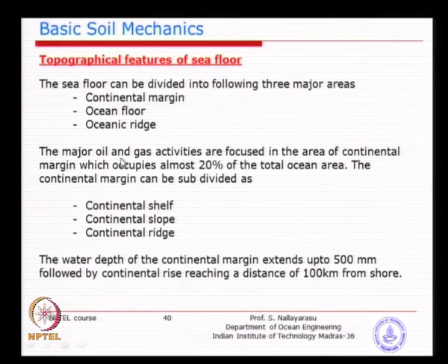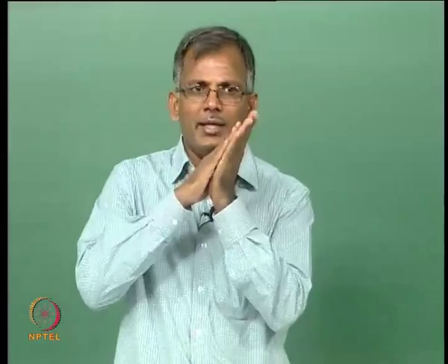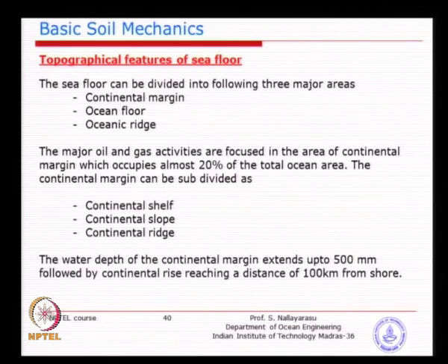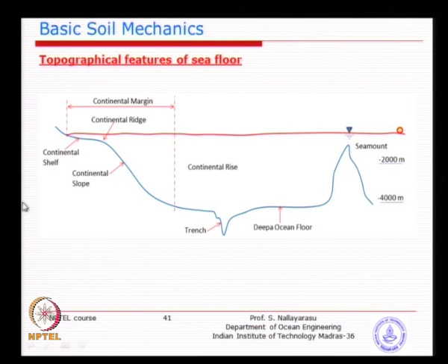So you could see here the variation of the soil. I think I showed two boreholes earlier, one from onshore to offshore, the other only onshore. Some layers are purely sedimentary in the marine deposition area, whereas in the land or interface area there could be a parent material. So when you do a soil profile, some layers may appear in this area, but it is not necessary that the soil layers go through the profile of the seabed.